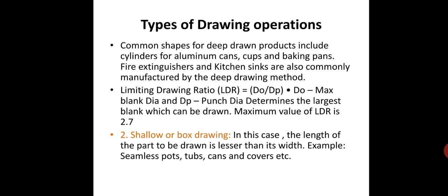Limiting drawing ratio, LDR, equals D0 by Dp. The maximum blank diameter and the punch diameter determine the largest blank which can be drawn. The maximum value of LDR is 2.7.